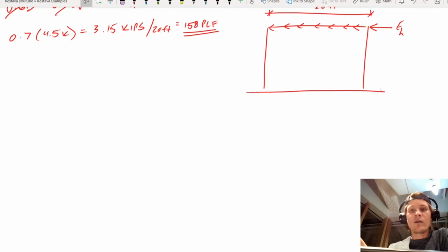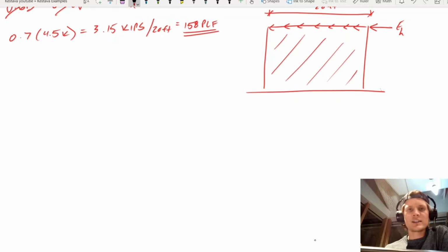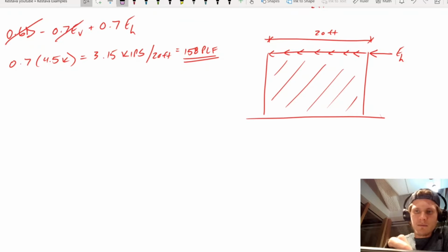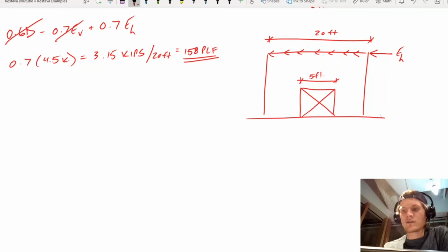All right, now that's assuming that this whole wall right here is just totally solid. There's no penetrations in it, there's no doors, windows, anything. You need to be careful, because actually, we'll just use the same one as an example. If there was a big door here, let's say that door is 5 feet wide, then you'd have to look and say, the shear is traveling across and through that shear wall, which means that up top, with my dashed line here, you have the entire length of sheathing all across the length of that wall, so you can distribute it all the way across that 20 feet.